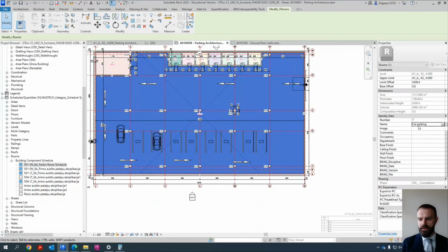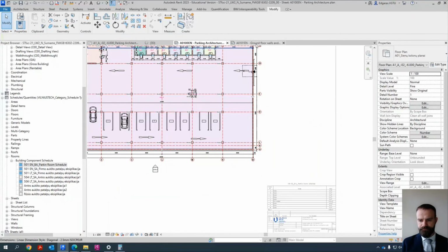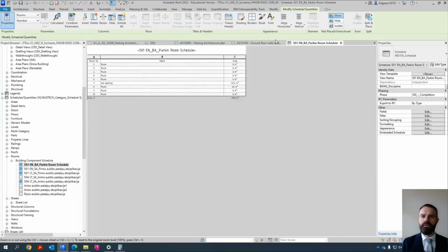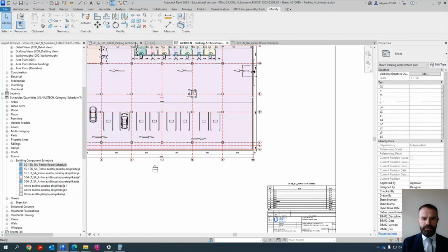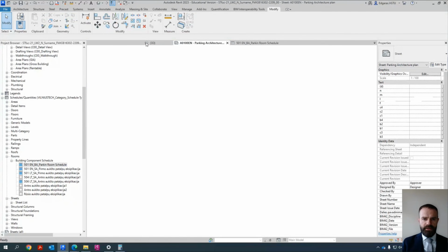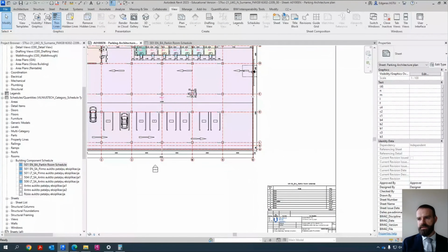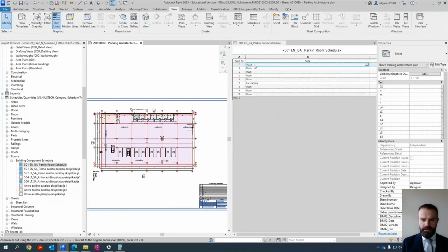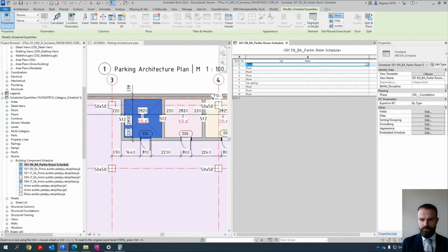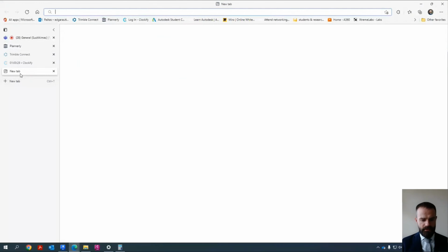I can do renaming on the selected element, or I can just tap on the schedule and put the objects side by side. So in this case, I turn off other views and use view title views, and I can click on the room and it colors the room. So storehouse, let's check out if my naming is correct.